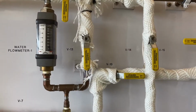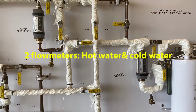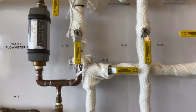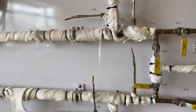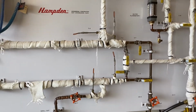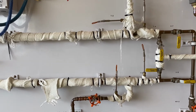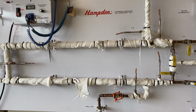We have volumetric flow meters on each one of the fluids. Again, we have hot water in this one, and we've got cold water. So, along with the thermocouples, with the flow meters and the temperature readings, we are going to be able to determine the energy exchange rates and the heat exchanger temperature profiles along the lengths of the heat exchanger.